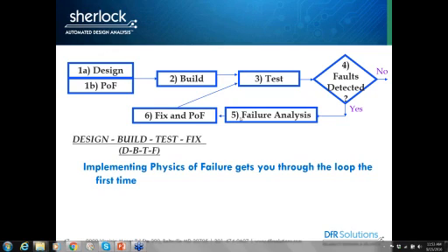We see hole testing, which is very limited as far as what is the fatigue behavior of the solder. But we have done that testing. It is something we are working on putting in the software, where you would specify where in your thermal cycle the vibration is occurring, and Sherlock would have to run multiple FEA analyses to determine that, because we have a lot of material property changes going on.